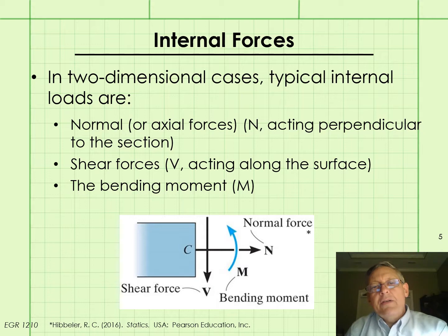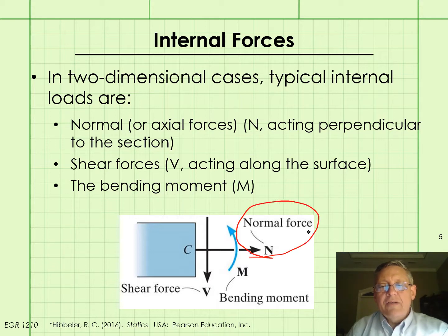So as discussed on the previous slide, for 2-dimensional cases, our typical internal loads are going to be a normal force, also known as an axial force because it's acting perpendicular to the cut along the axis of the beam, the shear force, which acts along the surface of the cut, and then the bending moment M.